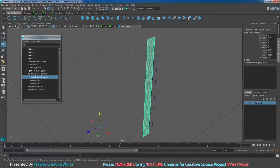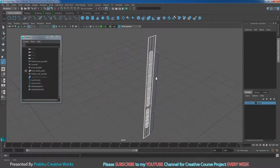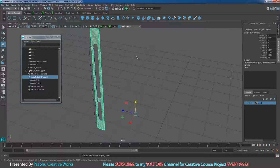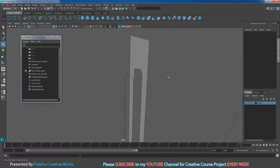So I will select this object. Go to surfaces and choose trim tool. Click anywhere on the outside. Don't select the inner holes. So click anywhere on the outside and press enter on the keyboard. So now we have a hole over here.